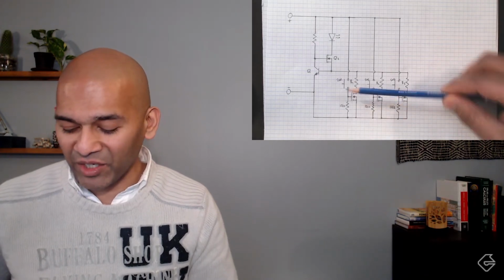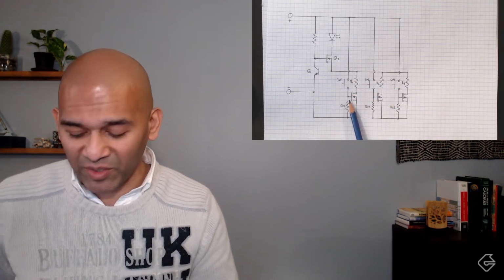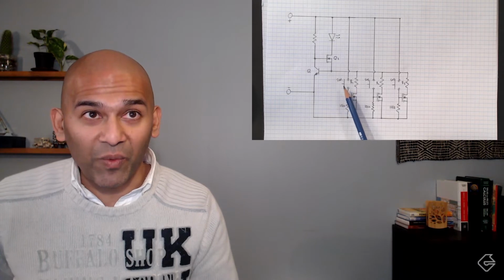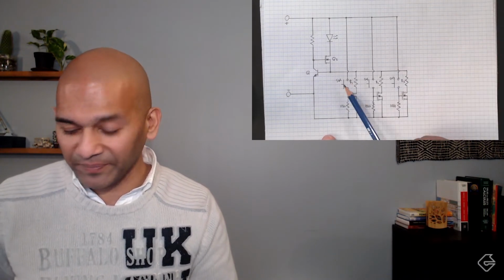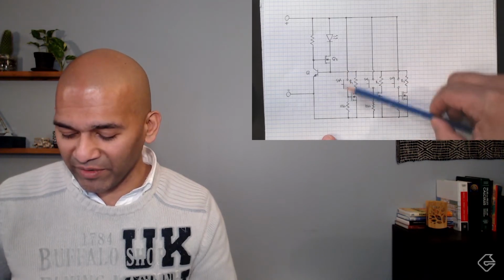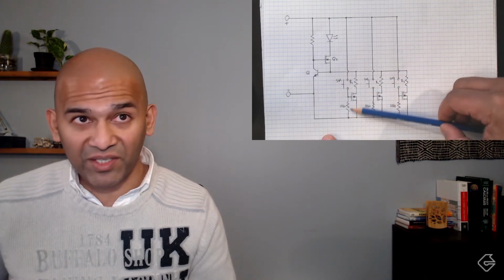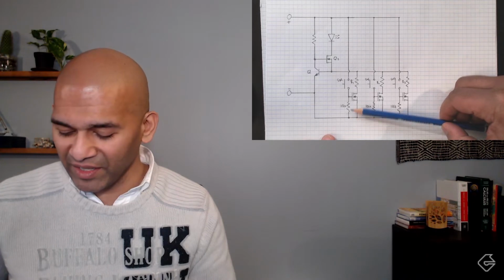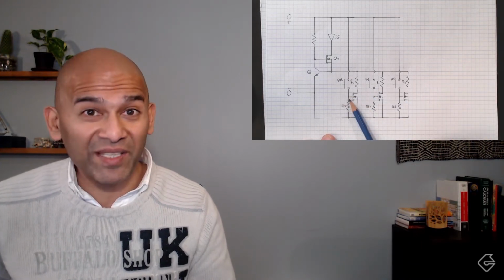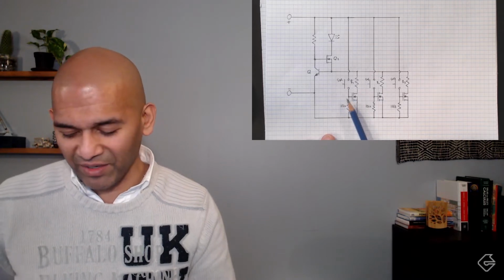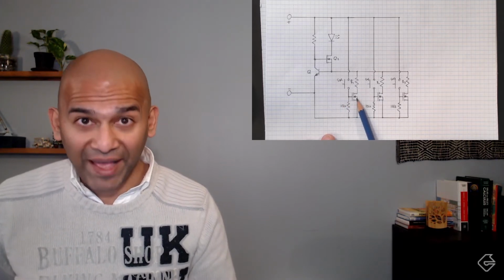So what I need to do is adjust the amount of voltage at this point, and that's what this switch is doing. The way this is wired up right now is that when this switch is open, this circuit over here is broken, and there's no current flowing through this 10 kilo ohm resistor over here. So the voltage at that point is going to be 0, meaning this switch is open, that MOSFET or the valve is open.